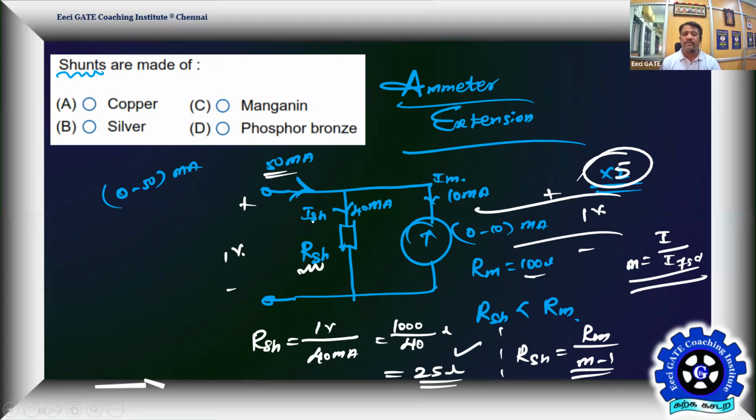The problem is that any metal wire subjected to a change in temperature is going to have the expression RT equals R naught into 1 plus alpha T. Any metal has a positive temperature coefficient alpha. As the resistor's temperature rises, because it always has a current passing through it, there is always power dissipation, and external temperature also will influence.